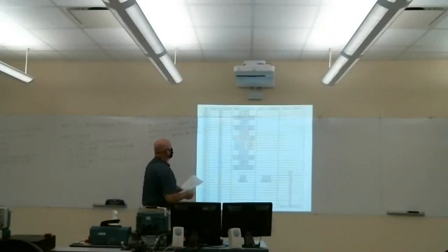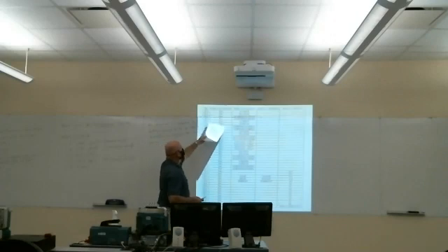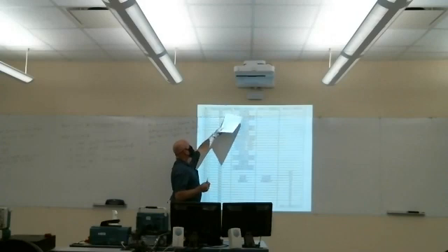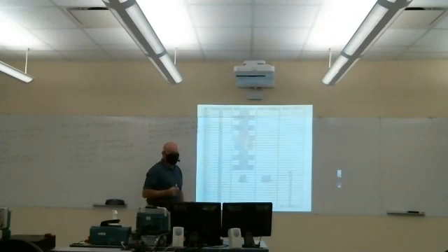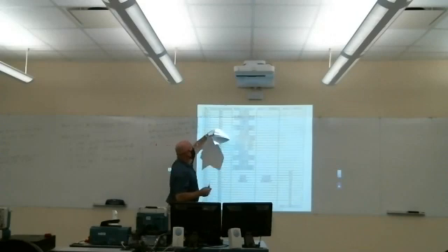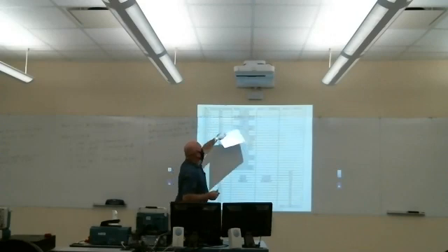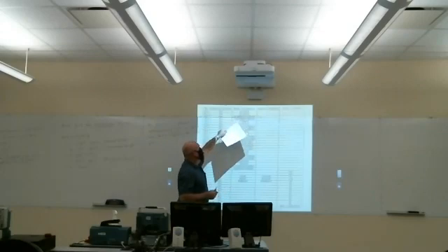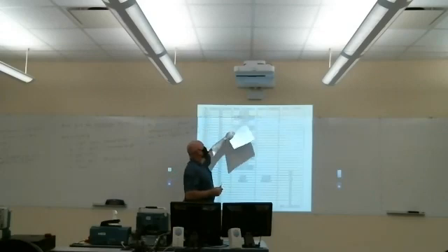So this shows, for the pin we were talking about, pin 1.2, if there's a 0 in the corresponding bit 2 position in the port 1 selection 1 register and a 0 in the bit 2 position of the port 1 selection 0 register, then it's used for general purpose I/O. On the other hand, if those two bits contain a 0 and 1 respectively, it's functioning as either a transmit